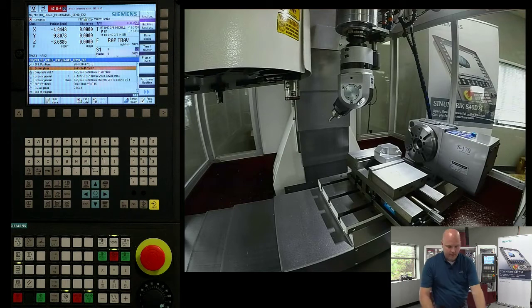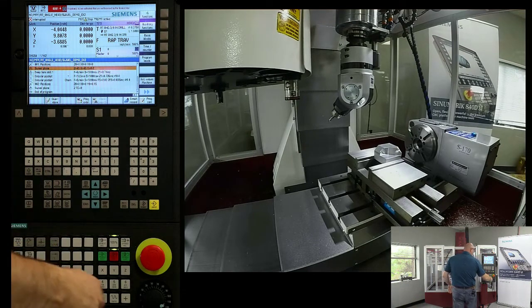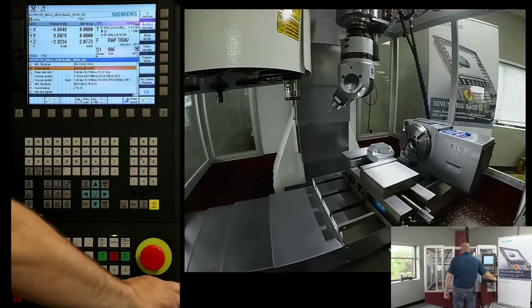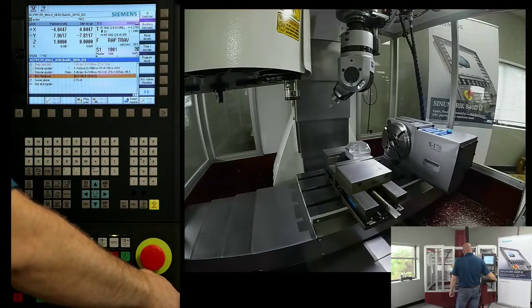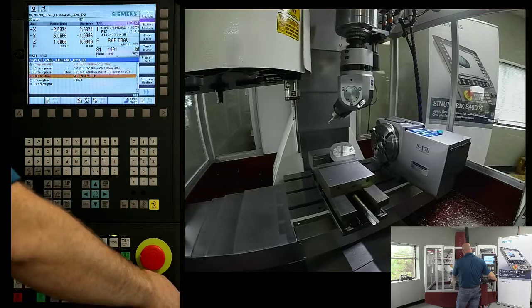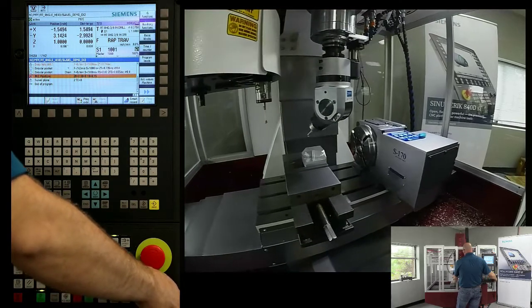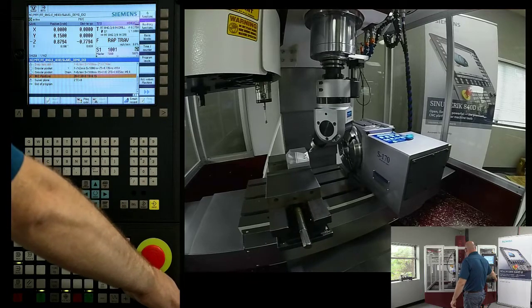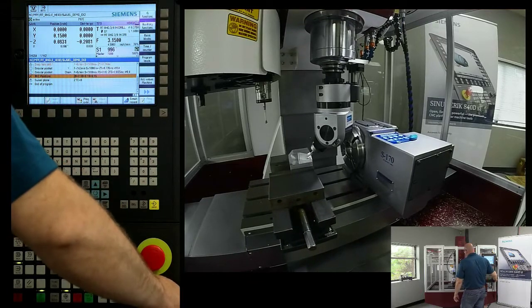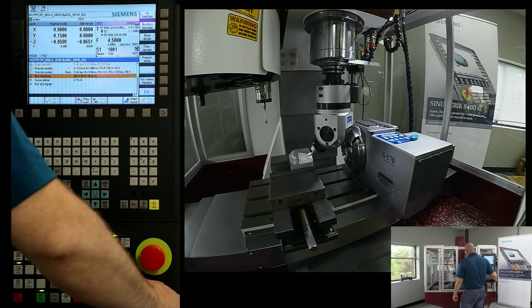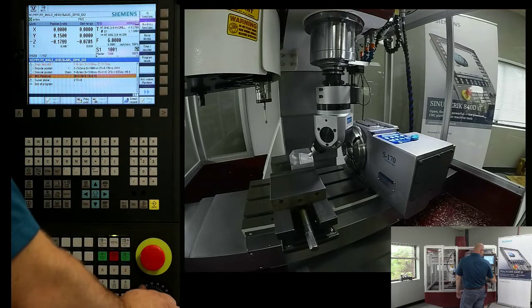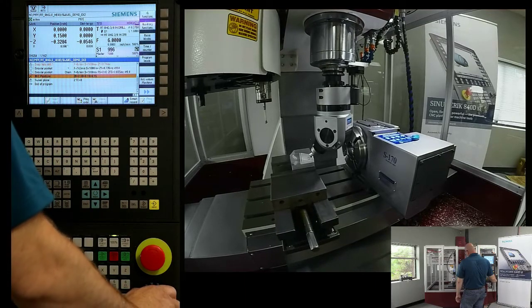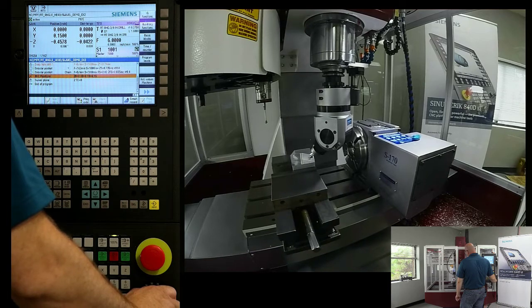Okay, so we are now adjusted at our 315. We initiate our cycle start. The machine is going to go up, and if you see the motion, how it's moving down, it's actually moving in what it thinks is an XYZ orientation. Give you a little closer view. And now our Z is aligned to this compound angle. And again, using the same style canned cycles, we're drilling at that orientation angle.